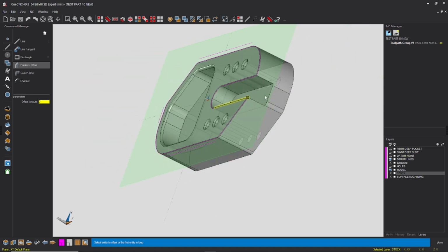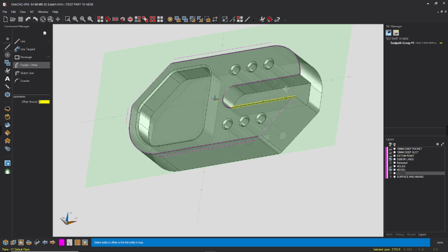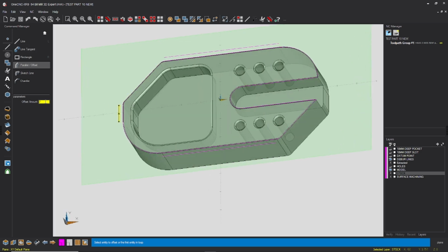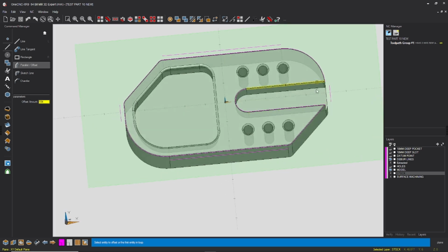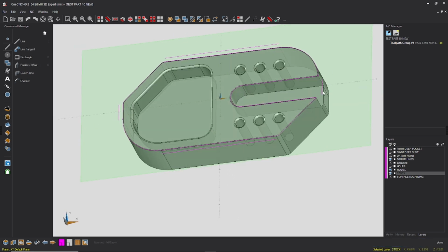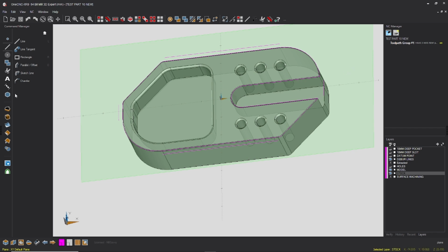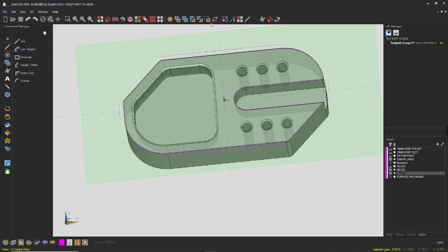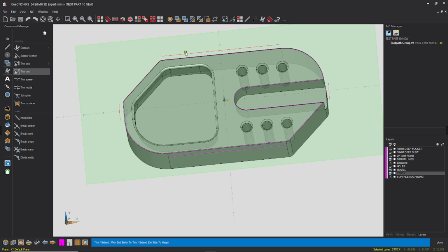Now, I haven't extruded this line here, and I'll just show you another way. The part's 100mm long in total. If I've offset this line by 2, the distance from there to there will be 102. So if I want 2mm the other side, it'll be 104. I could go down the path of extruding this line, projecting it, and using the parallel line, but there's no point. You might as well just use this. Trim these in with trim 2 again.